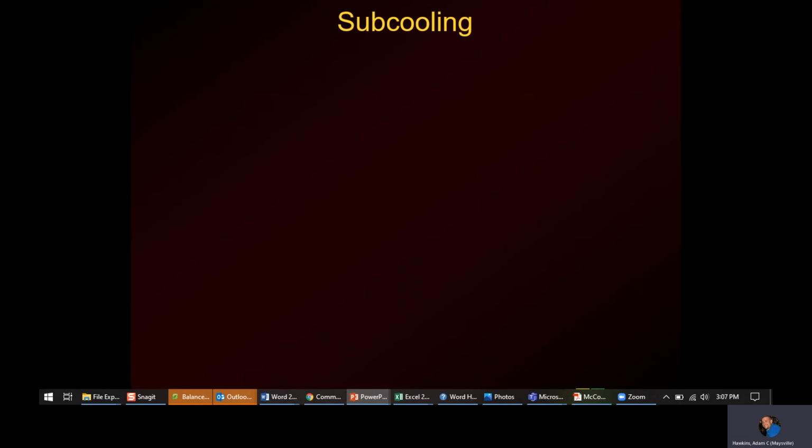If you're running 13, 14 SEER equipment, and I know we haven't talked about SEER a lot, but SEER is just the efficiency rating they're all rated in. If you're running standard efficiency, which now is 14 minimum, you're probably going to be running a 20-degree split. And if you're running an older system, you may see that 30-degree split.